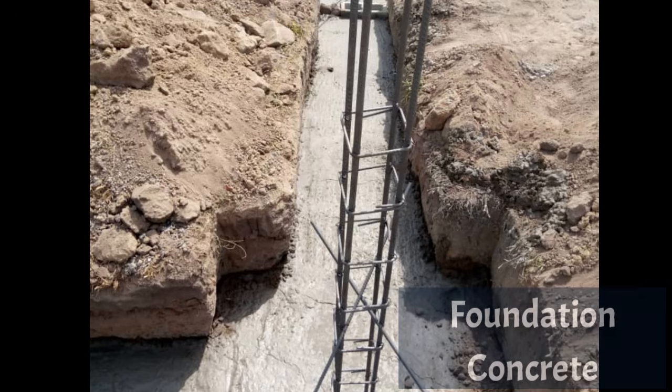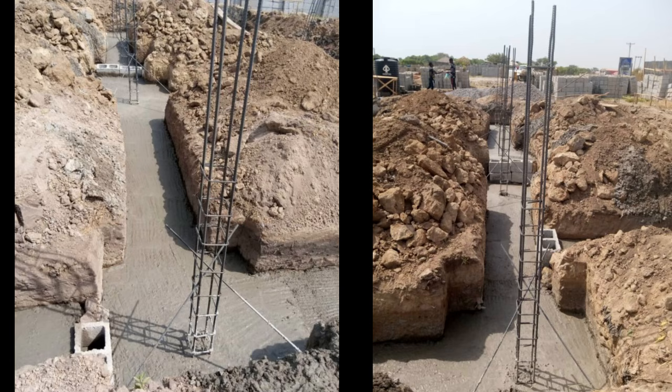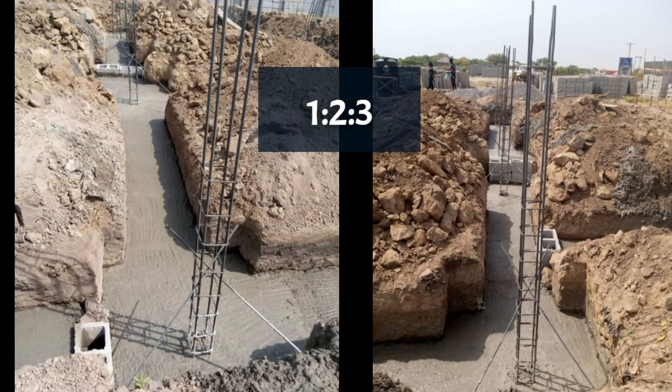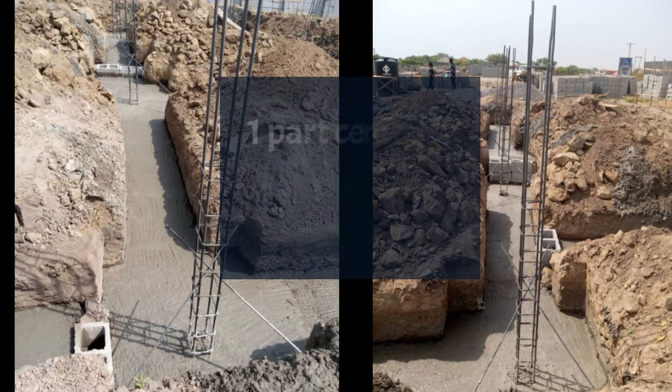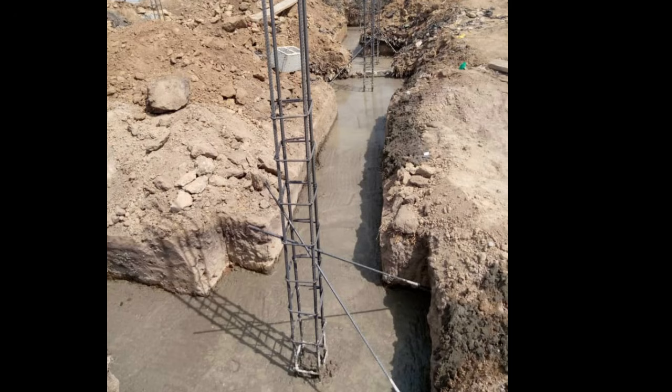The concrete in the foundation is one of the most important work items and should be done properly and to specifications. Because we were batching by volume, we used a mix ratio of 1:2:3, which is 1 part cement, 2 parts sand, and 3 parts gravel. This was done to improve workability and maintain concrete strength.